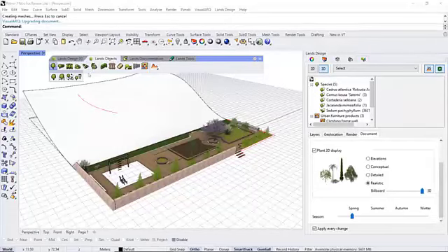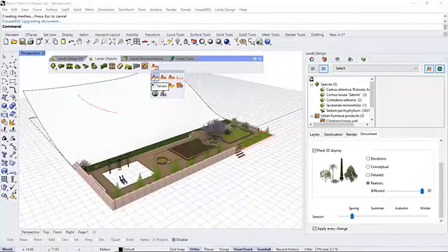Also, wrap any piece of geometry with this topiary command. We've got also a few civil work commands to insert walls, fences, stairs, paths, or rows of elements that we can browse from the library. Here we can find all the commands related to terrains. We can generate terrains from points or from curves or a mixture of them. We can apply some earth movement operations. Also, we can import from the web, as we have seen, or we can elevate curves, and on those we can create terrains.